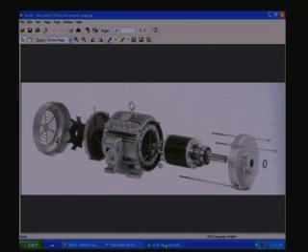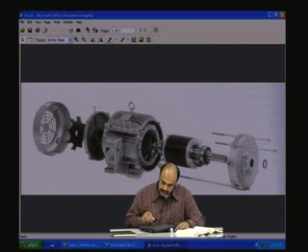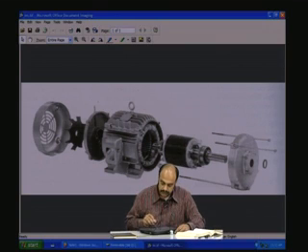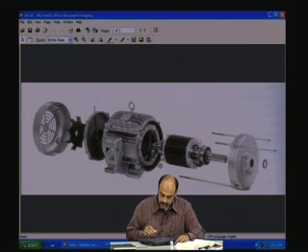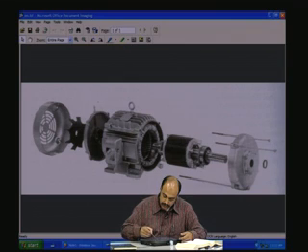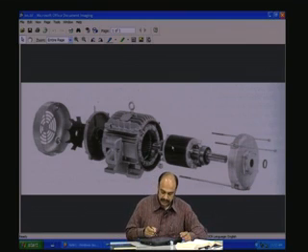Now look at the various parts. Let me move the cursor here on this part. This is the shaft and this is the rotor, and the rotor is aluminum die cast, and it is shorted at both the ends. You see this aluminum ring here shorts all the coils, and that's why it is called a squirrel cage.